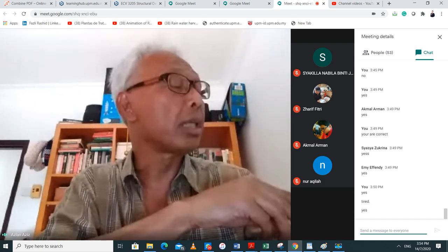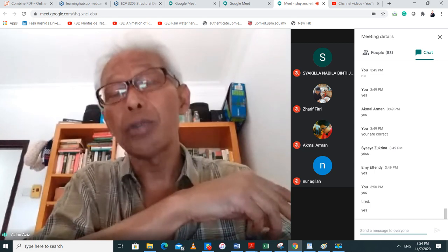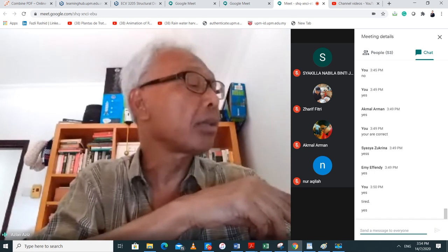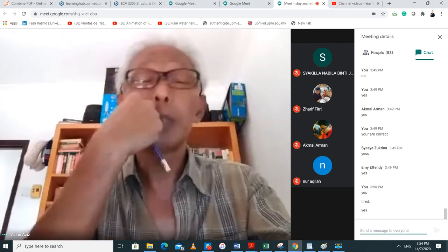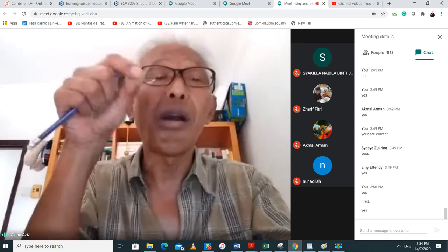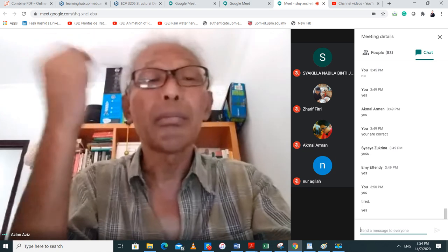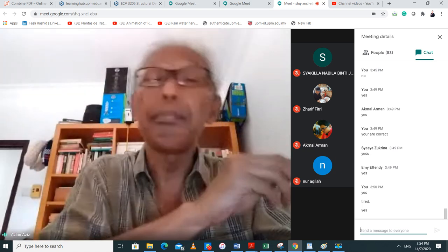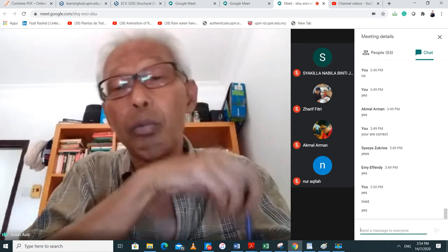And then for the second one here, it says low bearing. You thought that you have solid rock, but it's not solid rock because it has been crushed with time and erosion. Because when you do your SPT, you say that I hit rock. If I have my SPT more than 50, then I'm okay. Well, you may not be hitting solid rock. You may be hitting something like a weathered rock.